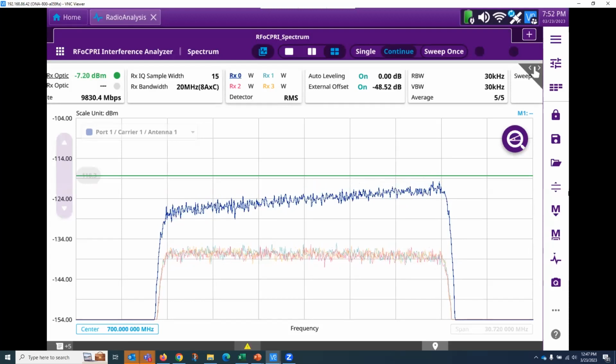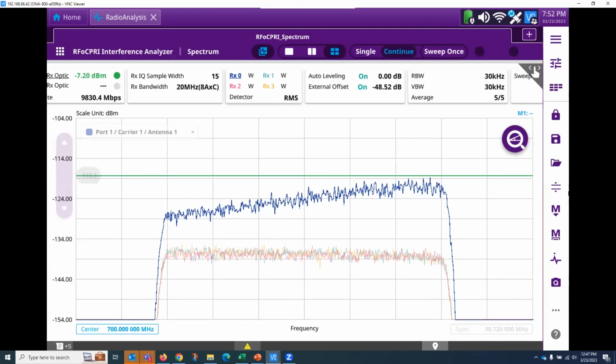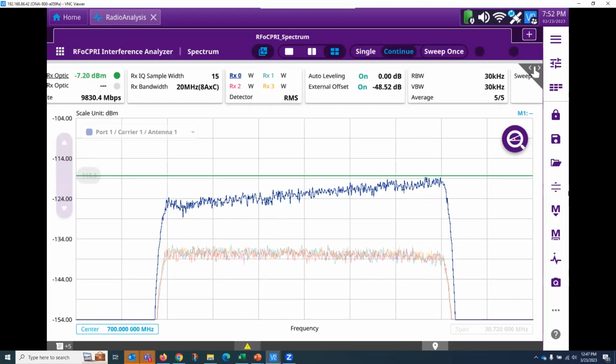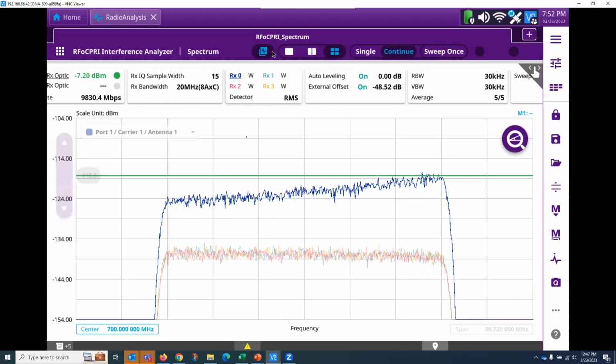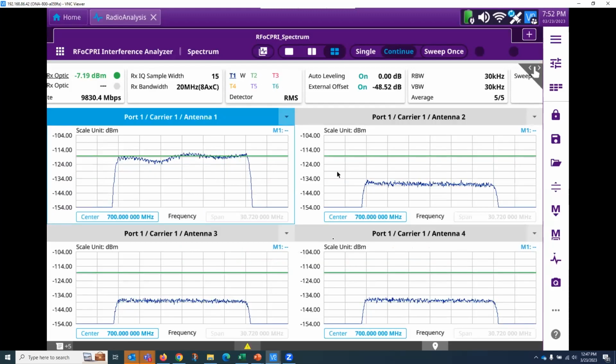Hardest question of the day is from Rami. Can you please explain how you can get the same spectrum carrier on 2 different power amplitudes? Okay. So if we go here, we separate the screen into just 4 quadrants, if you will. It's the same spectrum analyzer screen with our power values here on the left side. So we use a dBm axis, and I set some leveling on so it would fit nicely in there to somewhat realistic numbers. And in a real spectrum analyzer, you're going to get 1 amplitude at a time because that's how a spectrum analyzer works.